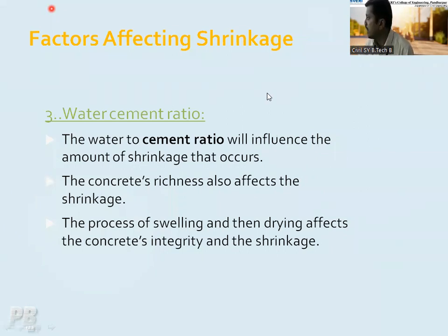Okay. So I think though maybe we can't have control on the creep, it is not like that. If in the early stage, you have constructed a home and within 2 months you see some cracks which have developed, that is not the creep. It's a big deformation. It may be due to faulty execution work. The results are different for that case. Creep is a permanent deformation with respect to time. As the age of the concrete proceeds, there is a deformation internally.